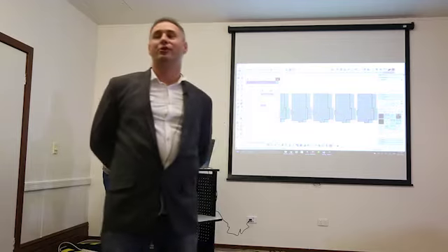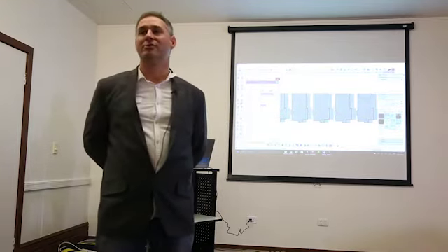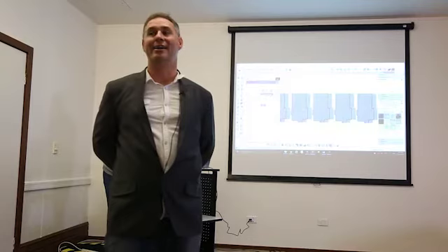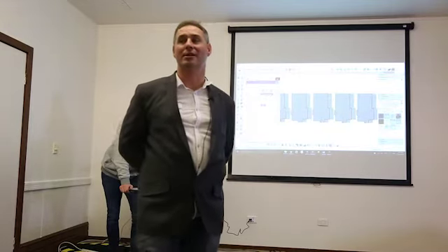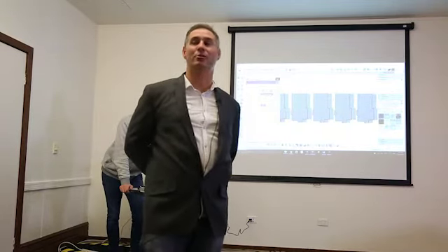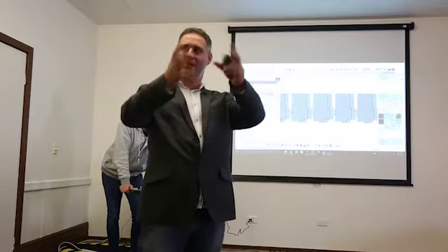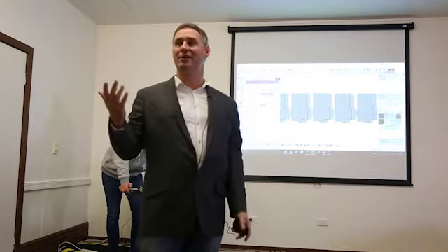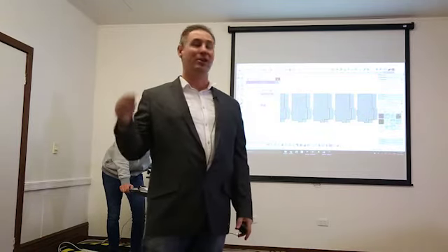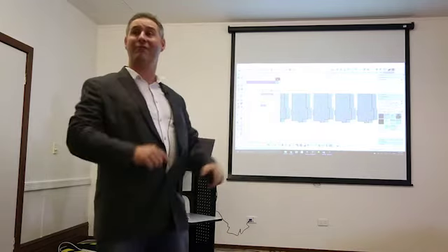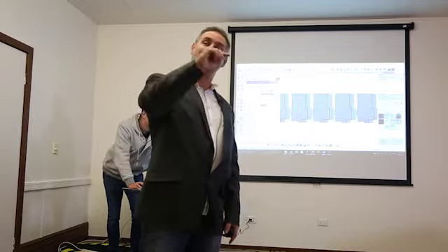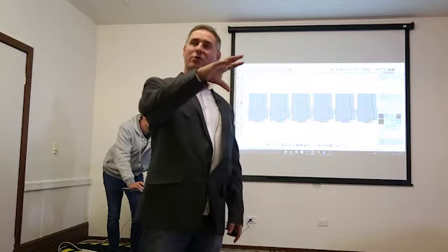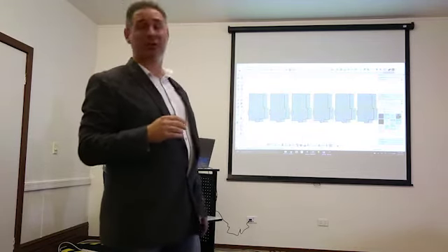Okay, when you put in the Google Earth map, it knows where it is. It knows the minutes and seconds from the equator, and you don't have to worry about solar north or magnetic north because it is as per the globe. Plusspec took a Google Earth round drawing and put it in, and therefore it automatically knows where it is in real life. You can then take these models and go file, upload to Google Earth. If you don't want to share the model with the client, share them a link with Google Earth and say, here's your house that I've drawn for you. It's a bit clunky, but it works. I usually share models with my clients.